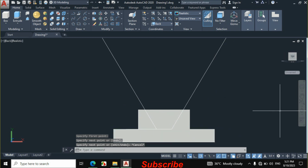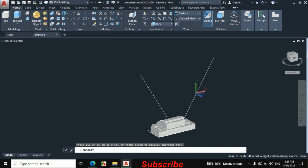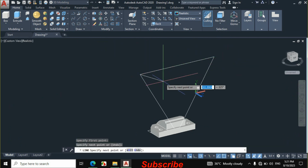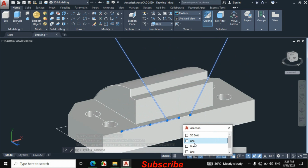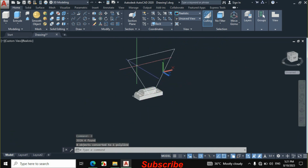Press escape and orbit it. Now again click on line and join these two lines, escape. Now select these lines and this line and enter J from the keyboard for join. So this part is joined.